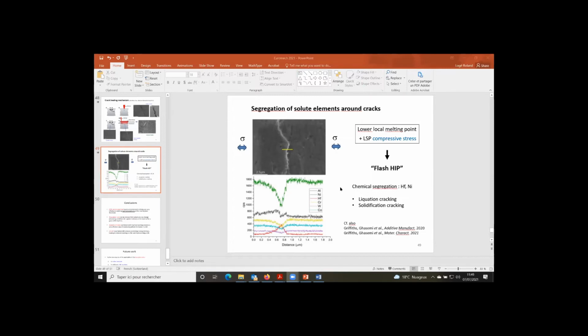Maybe, okay, one very last question and then we stop this session. Pushkar, please. Yeah, can you hear me now? Yeah, thanks for the presentation. It was interesting, but I have one question just out of curiosity. In laser shock peening, a nanosecond pulse laser was used, and I believe you also need a transparent layer to confine the shock wave that generates the compressive stresses. But I have read in one paper that with a femtosecond laser, you can also do a shock peening treatment in air. So do you think it's a viable alternative to the nanosecond pulse laser?